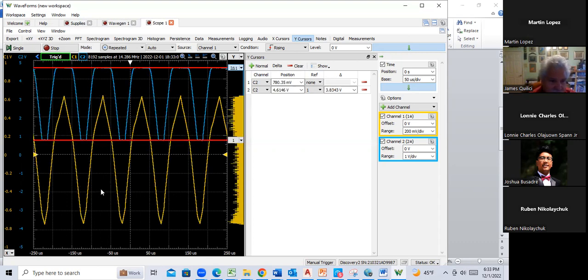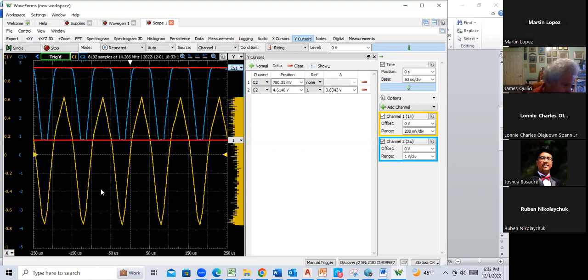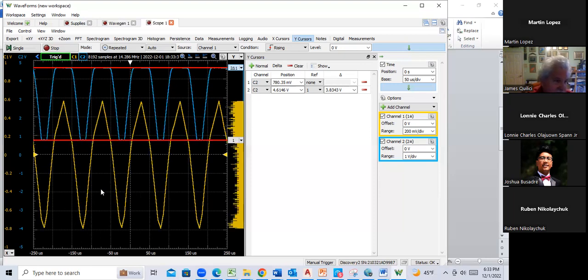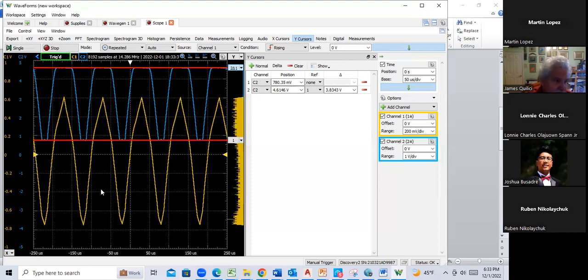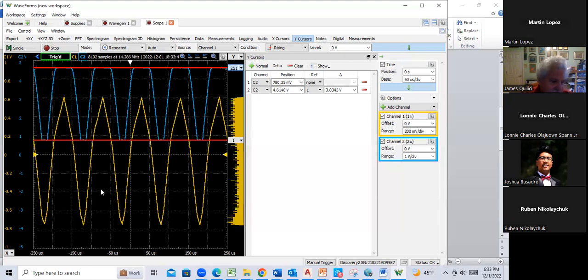But anyway, so that's basically step 10, defining where your peak to peak is. And it says compare the results with your specification. The specification didn't specify where the clipping occurs or anything. What you want to do though is you want to get your waveform. If it says that you need to have 2 volts peak to peak min, then just demonstrate and take a screenshot showing that. You're probably going to have to adjust your input voltage, but take a screenshot and demonstrate that you got 2 volts peak to peak.